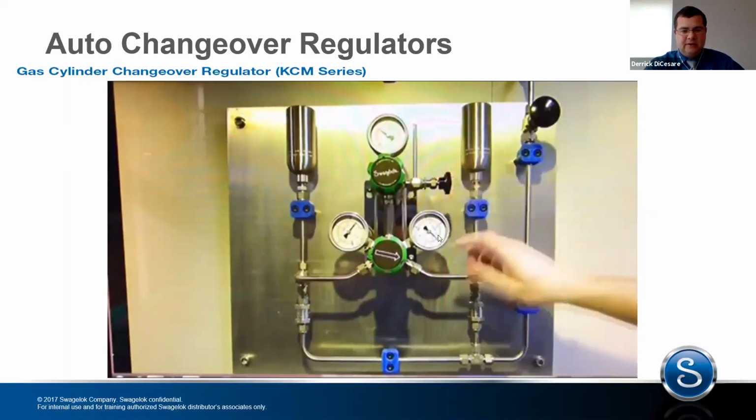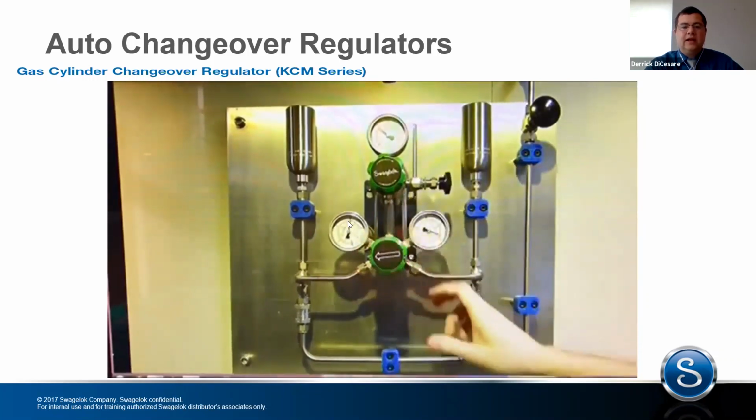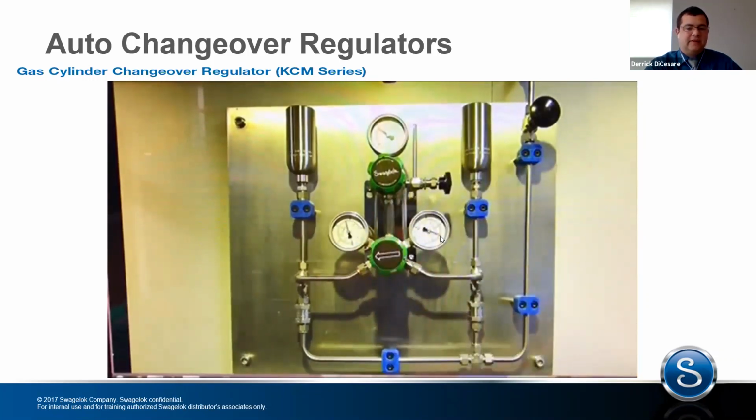So we're pulling from the secondary supply right now, but we've just replaced our cylinders. We're going to kick that over, and now we're running the primary pressure instead of the secondary pressure. So again, the nice part about this, there's no interruption in gas flow. The flow is going to stay exactly where it is because you're doing a two-stage pressure reduction, so your supply pressure effect is taken into account with this, especially in this case where you're running such a small volume.